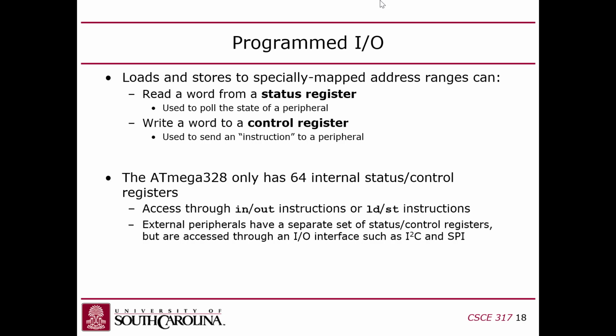So let's talk a little bit more about these I/O pins and how you read to them. When you're doing software hardware interfacing, there's really just three ways that software and hardware talk to one another. There's programmed I/O, which is where software will execute a load or store instruction that resolves to a special address that doesn't map to memory but maps to a peripheral, meaning that they're mapped to a control register or a status register.